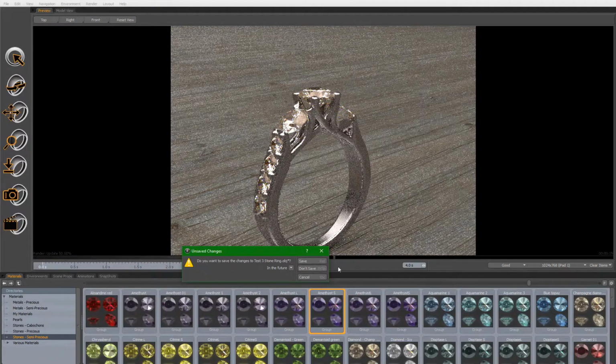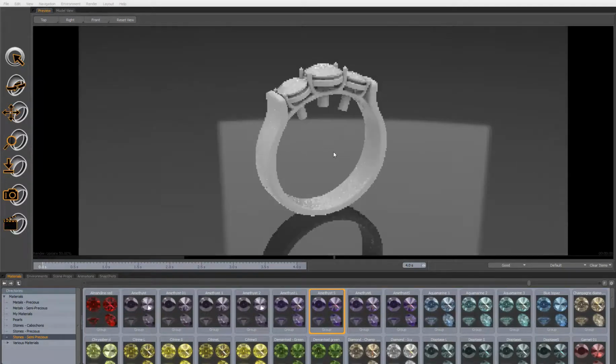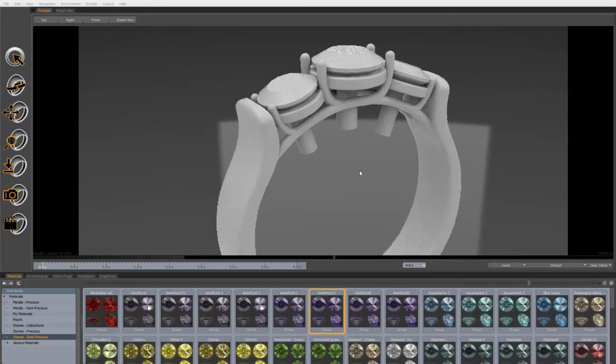I also want to show you a feature in there. Okay, so this ring, you can see I've included some stone cutters in here, and as you may know, cutting those out of the actual metal for a production piece is usually not a good idea. Some setters don't want you to pre-notch your stones, but then you have to set up a whole other file with all of it cut out for the rendering, because these stones look much better if there's not metal intersecting into them. So we can now just import your cutters in and not have to actually Boolean them.